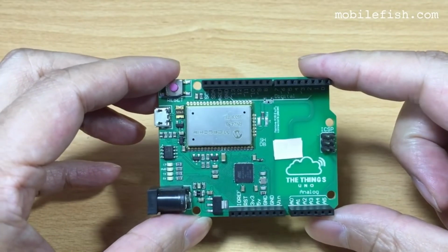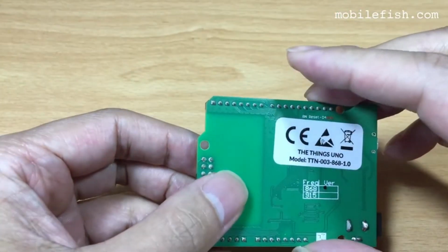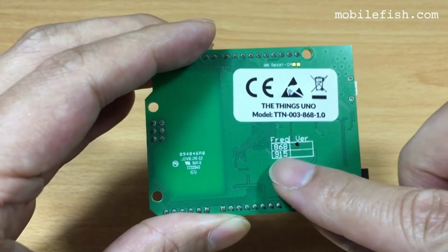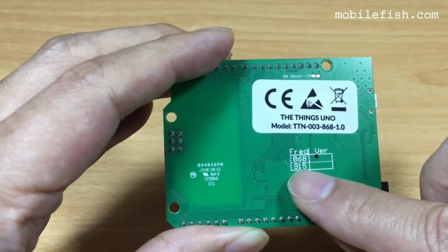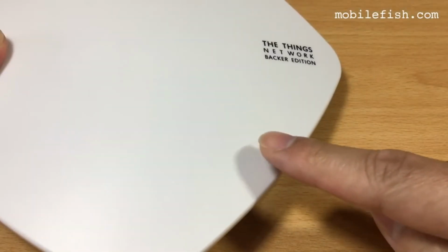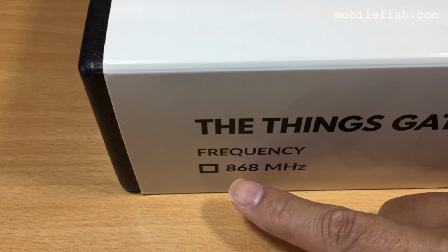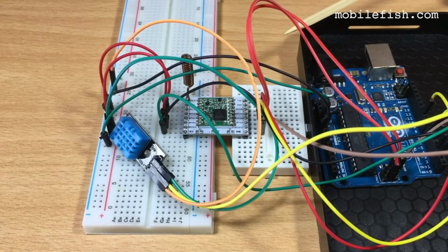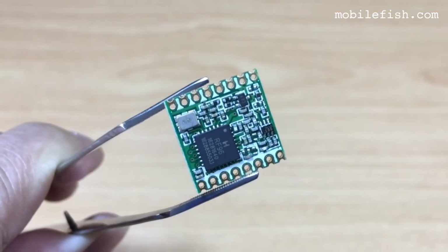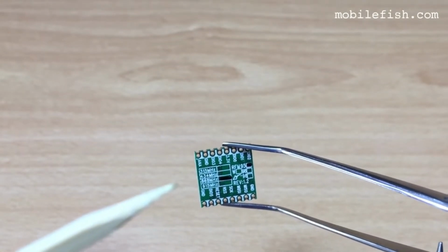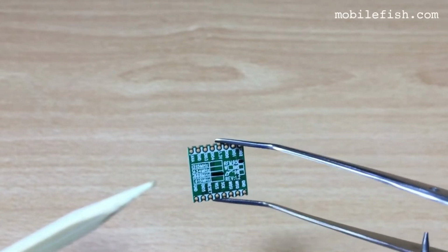If you buy a LoRa development board, always buy one with the correct frequency which applies to your country. If you buy the wrong frequency, you break the law and it will not work. The same applies to the gateway. I live in the Netherlands, so I have to buy a gateway using this frequency. If you build your own LoRa node, you can buy these radio modules. This is such a radio module. And as you can see, I have bought one with 868 MHz. Never buy the wrong frequency.